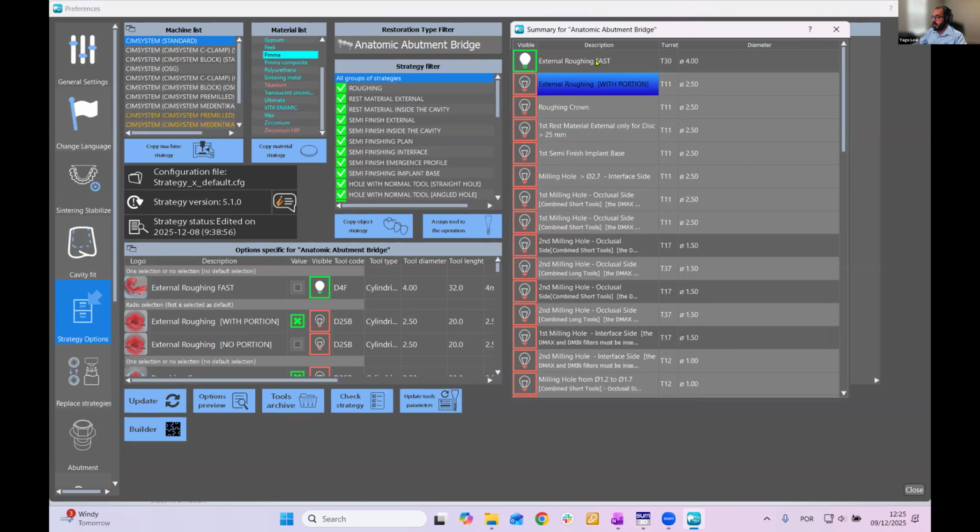That is something that I will explain in a moment, because usually with those tools here, you see different tool changes, but this necessarily will not happen because those are the drillings, and we have drilling with a short tool and with a long tool. So usually this tool path will only be enabled if this tool is not able to fully mill the entire length of my screw channel. Okay, but here you can double check exactly what is going on with your strategy and the order.